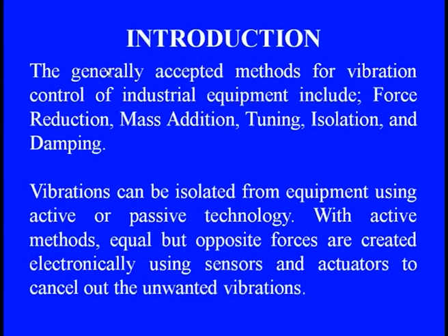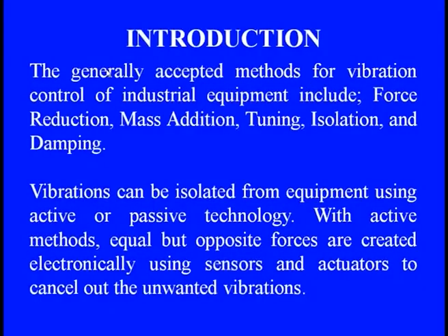So in a general way, we can say that vibration can be straightway isolated from the equipment using these, either the passive technology by adopting some external devices, or by active technology by reducing the force through electronic manner. And with the active forces, the forces which are quite active at the point of contact, or at the point of this misalignment feature, we can adopt even active vibration control by creating the force electronically, using smart sensors or actuation with smart materials, to cancel out these unwanted forces coming out through whatever the machinery features or the rotating part of the machine.